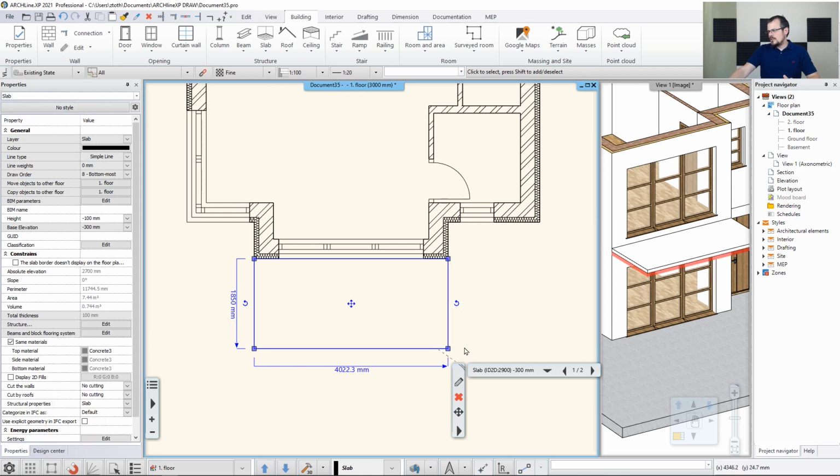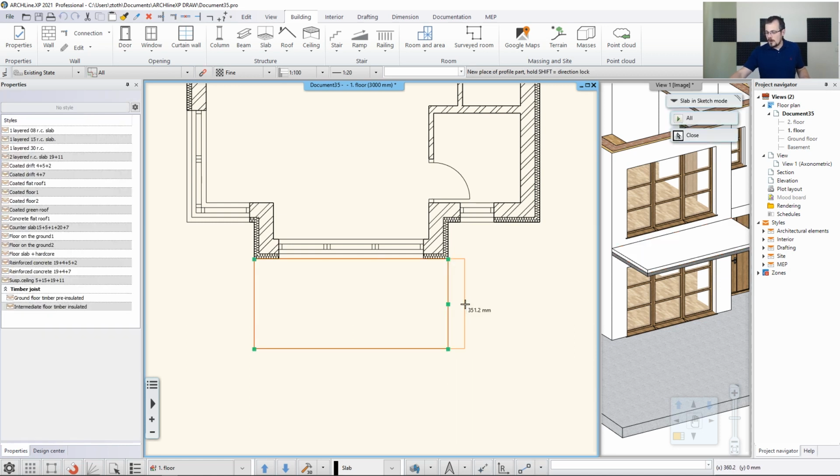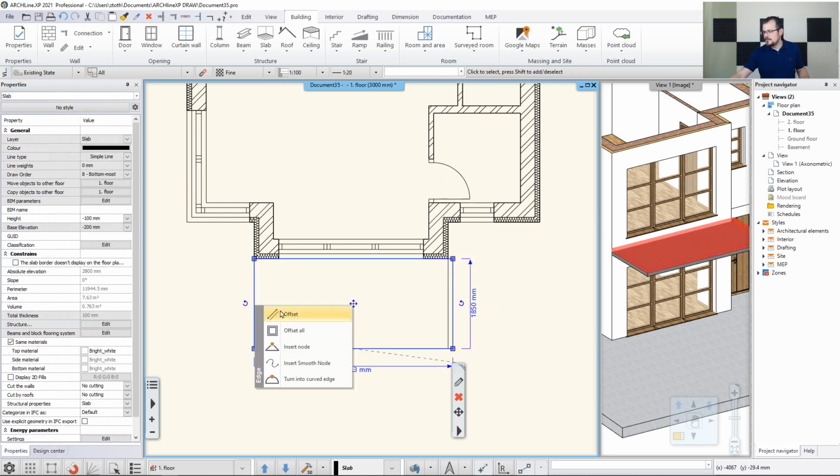First of all, you select the slab that you want to work with. Now, here's an interesting thing. You selected the slab, but the software is not really sure which slab you want, so it gives you a choice, like a toggle between the two elements which are overlapping each other. So by clicking back and forth, you can find the actual slab that you want to work with, and now we have the top one selected that I actually want to extend. So I'm just clicking on the sides, and I'm going to offset most of the sides to 100 millimeters.